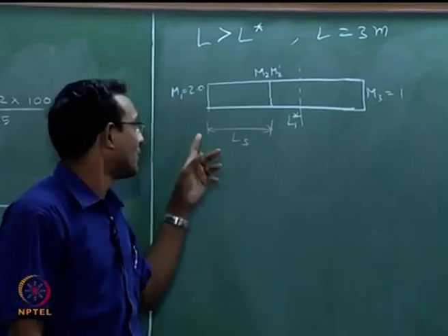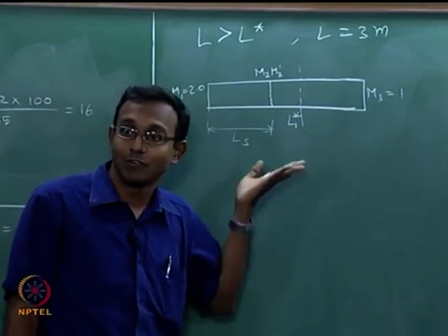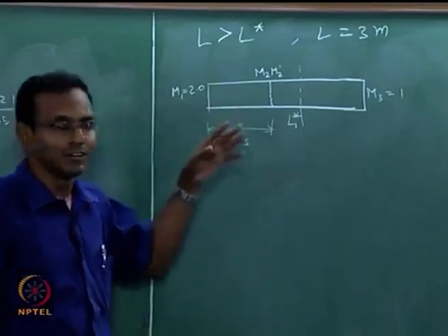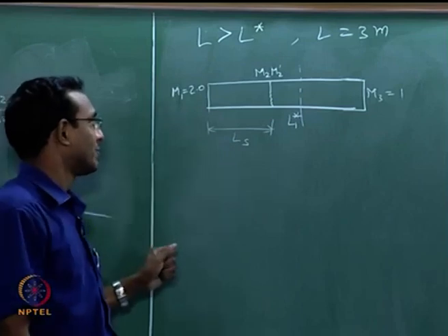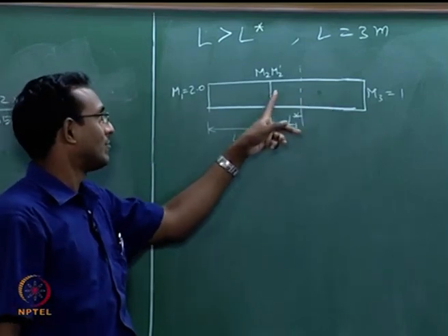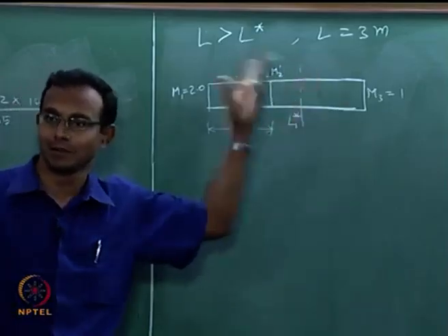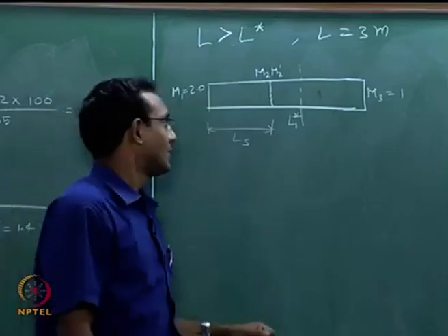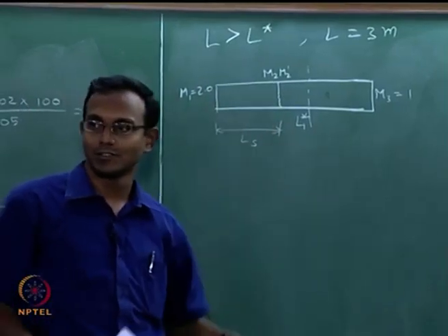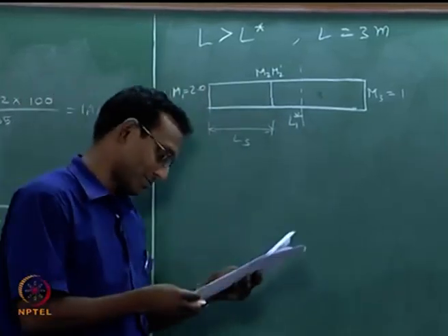I am just doing Mach number variation with a shock in my tube. Of course, I know that once I know Mach number distribution in my tube, I can find any other property because I have Fanno flow tables with me. For a given Mach number, I can just go and find any other property. If I want to find, say, somewhere in the middle, I can just calculate from M2 prime with F and DH, and I can solve that problem. It is not very difficult. If I want P by P star, whatever, I can get every number, so I can find pressures also. I am not solving those, but I will probably give you those as exercise problems.